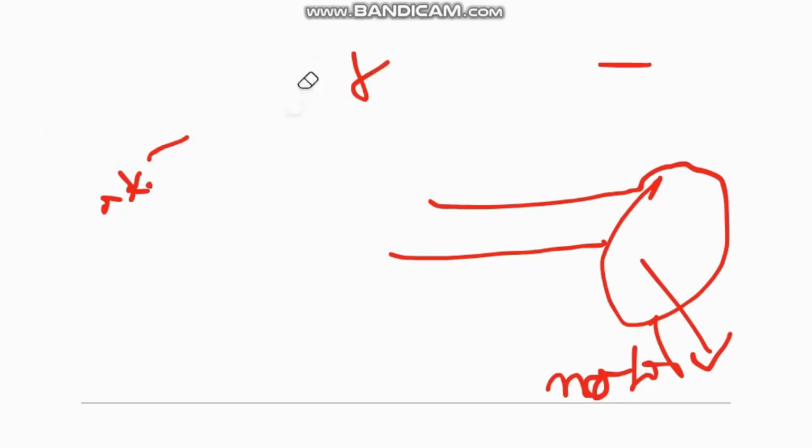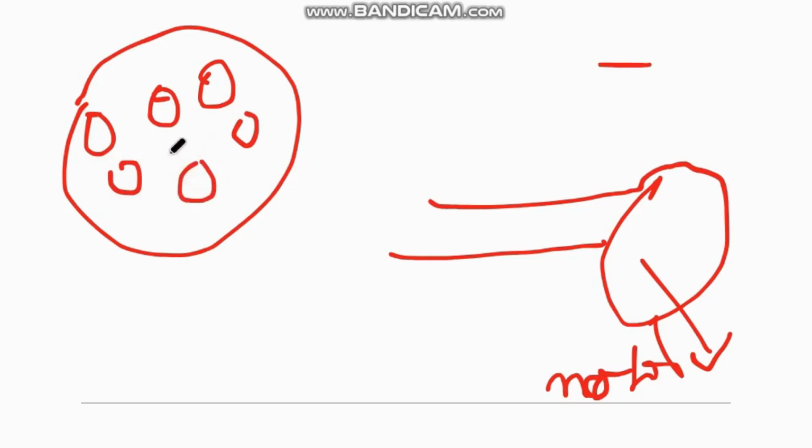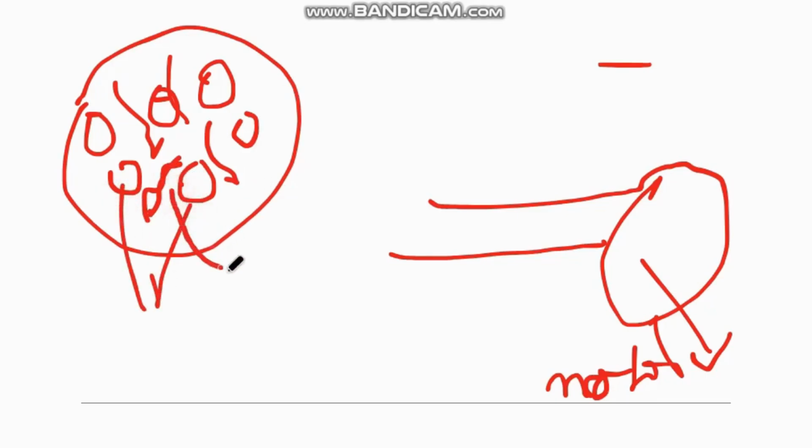The next one is attrition. In this cylindrical vessel, when these balls undergo circular motion, there is friction between these balls. And due to this friction, whenever the sample comes in between the balls, it gets rubbed by these two balls, and this also causes size reduction.